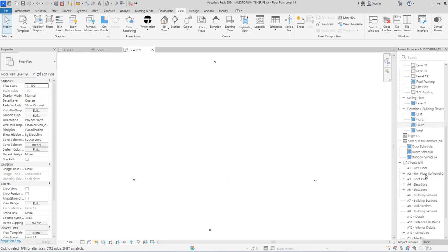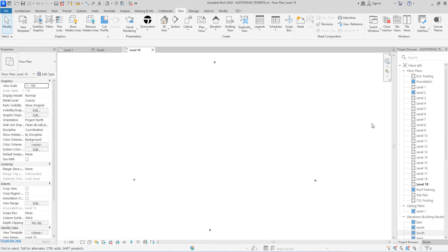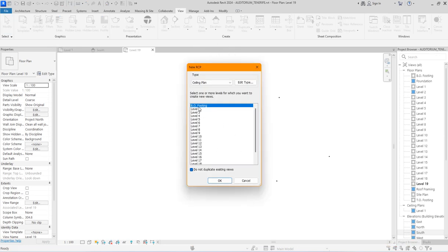But when you look at the ceiling, you are not seeing it in the ceiling. So the problem still continues to exist. So what will you do? You're going to go to that place and do the needful. So let's go back here and go to view again, and you say reflected ceiling plan. So you click on this one. So everything here is there. You're starting from level 2 because only level 1 has its ceiling reflected.